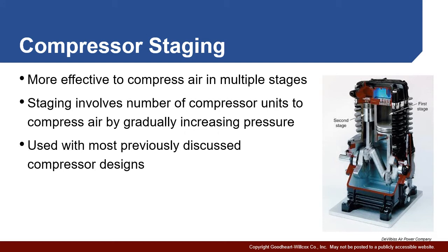The compressibility of air tends to be problematic for pretty much all of these various compressors, however. The fact is, as the pressure goes up, the volume goes down, so it's very difficult to get a very high pressure out of a system with one pumping cycle. So the solution to this is to have compressors be multi-staged. So for example, we see an inline compressor here.